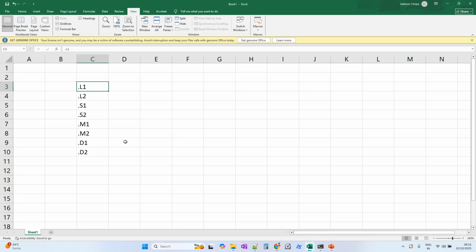So what we will do is, we will first load LDW. We will do LDW, and so for 2 values we are loading. 2 16-bit values we are loading. LDW is load word. Then after how many cycles can we use it? 1, 2, 3, 4. 5th cycle we can use it.